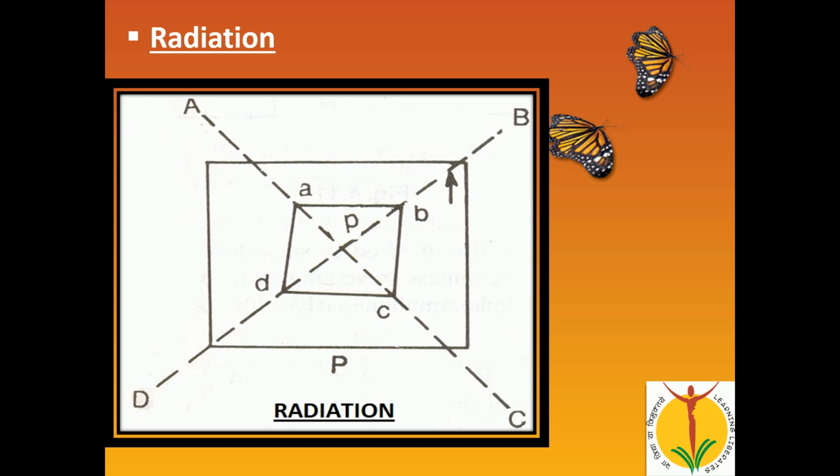The procedure is simple. At ground point P, you are going to place the table exactly over this point, and through the U-fork you are going to take this ground point P on the drawing sheet. These capital A, B, C, D are the ground points, and those ground points we have to take on the drawing sheet. When we have taken point P exactly on the drawing sheet, along with it we have to use the alidade, fix the point P, with the alidade touching point P and bisecting the ranging rod at capital A, we are going to draw the line.